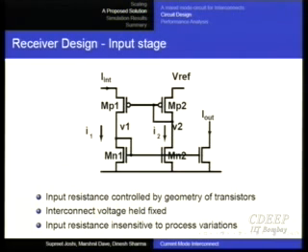Right? So this is what we end up doing. In short, this is the weak point of this. That means I have to convert this current to voltage. Okay? And the current comparison, I have to compare this current to delta I, to 2 delta I, to 3 delta I and give an output whether the output is 0, 1, 2 or 3. Right? This comparison tends to be slow, unfortunately.